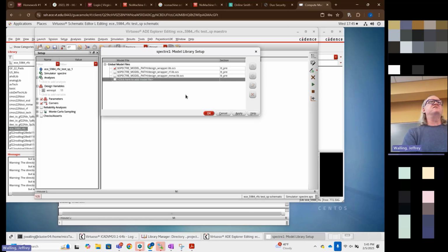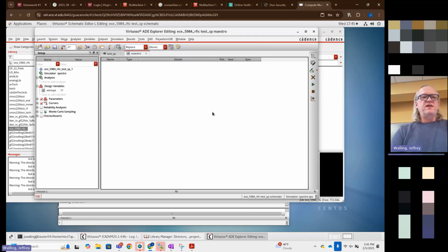The one caveat is you are going to be working on RF and microwave components, so oftentimes you'll want to choose the millimeter wave library. In general, each of these things supersedes each other. So if you choose the millimeter wave library, it has all the other standard components plus additional millimeter wave components. In our case, this won't matter because we are not using any library components.